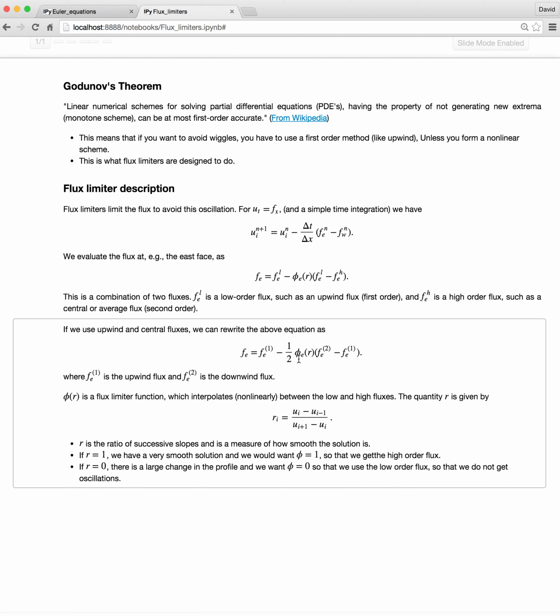And so you can see that when phi is 0, you get the upwind value, and when phi is 1, you get a central difference, and when phi is 2, you get the downwind. So it's kind of like interpolating between upwind, downwind, or central, a kind of equal weighting between the two sides of the fluxes.